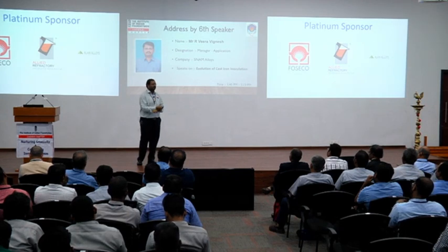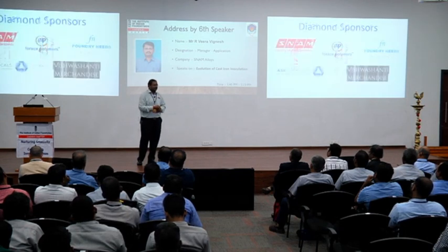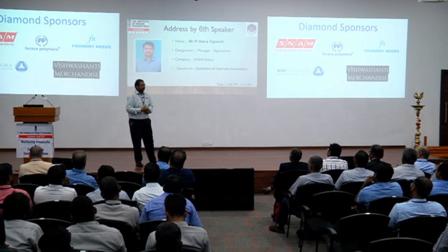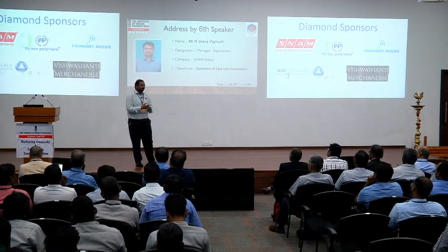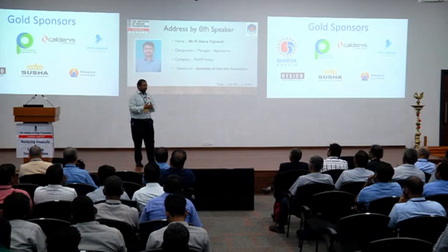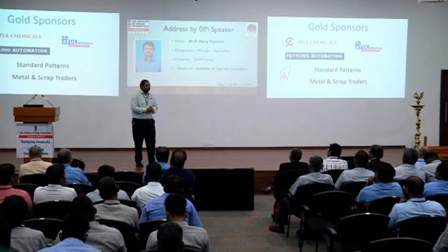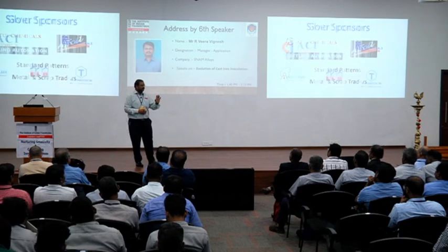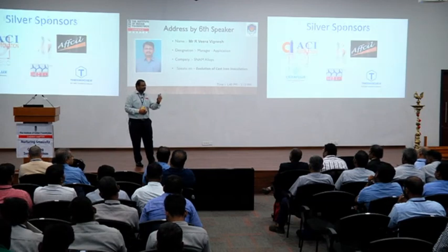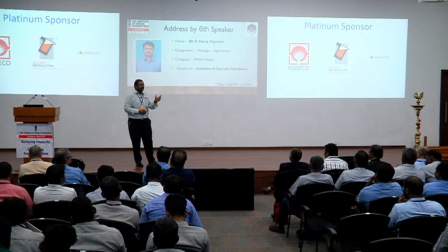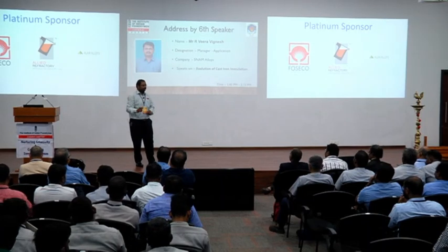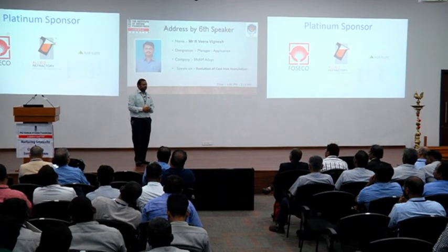Amount of dissolved oxygen I can tell directly, but there is no measure right now available, sir. So it has been arrived at through different trial and errors, and inoculant with less than 0.5 aluminum, there is no existing inoculant like that. So it is like silicon is balanced by calcium, silicon calcium is balanced by aluminum, and this combination gives you some effect. So it is arrived at that level, sir.